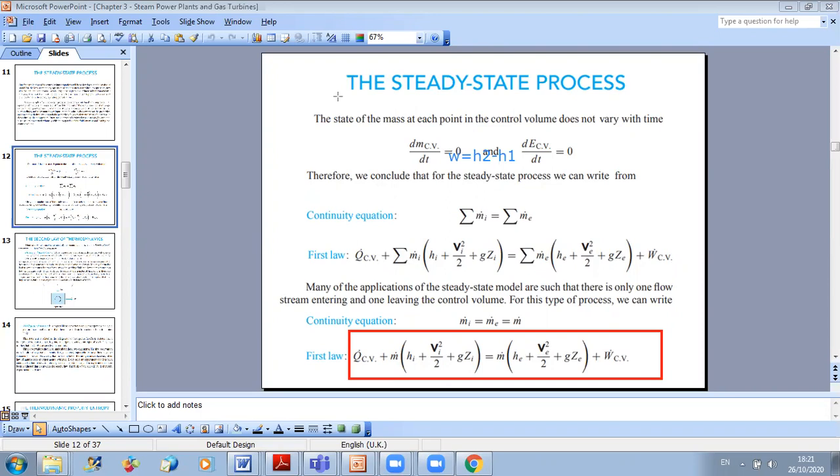So you can see here, what is happening in your compressor? In your compressor, no heat, so this term cancels out. If you assume no variation of kinetic energy, and as I told you last time, in general when you have a fluid circulating and they don't give you any information, you can consider that the kinetic and potential energy are very small compared to the enthalpy, so you can neglect them. So you end up for the pump with the work in the pump, W pump,